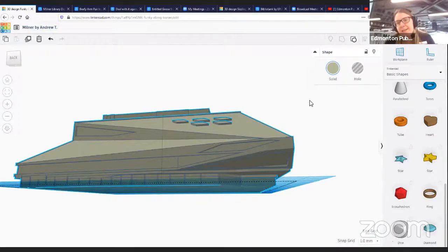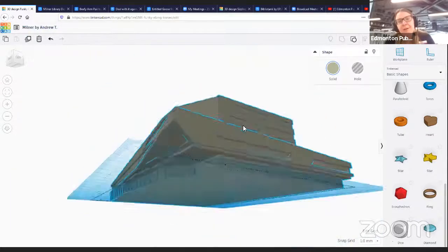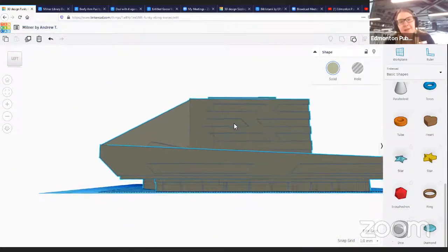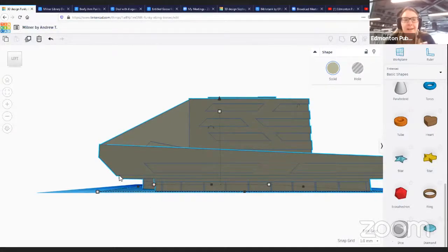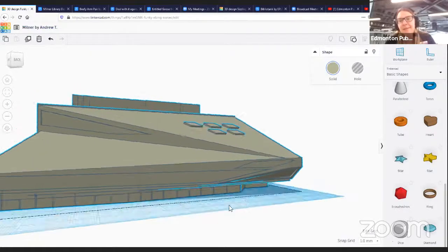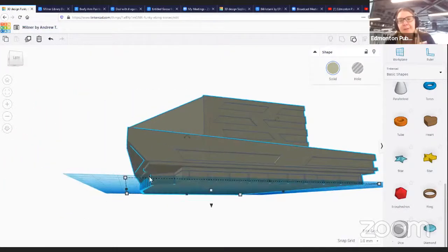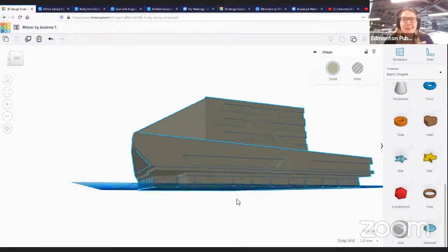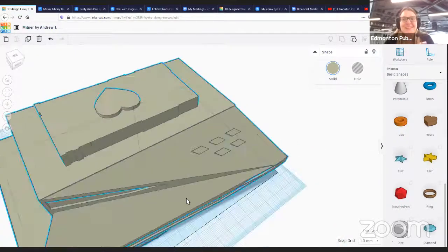Just talking about this as something that we would 3D print, one of the pretty big challenges that our fused deposition modeling, our FDM 3D printers face is unsupported 35 or 45 degree angle, greater than 45-degree angle overhangs. So this model actually, if we were to print it out for real, we may need to add some supports, because that's a pretty sharp overhang there, and we wouldn't want the plastic to get dropped and for things to start to droop. Nobody likes to see that on real buildings, but definitely not on 3D printed ones either.